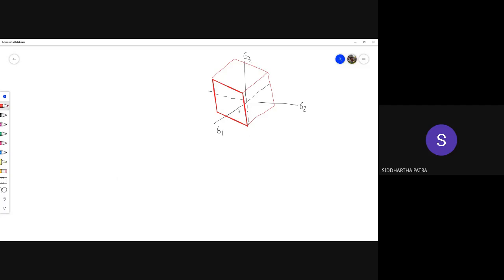The maximum principal stress theory is given by this box, just like it was given by a square in a 2-dimensional plot. The maximum principal stress theory in 3D is a box where each of the planes is either plus sigma y or minus sigma y. So it makes an intercept with one of the principal directions at plus sigma y and minus sigma y, and it's a plane parallel to the plane of the 2 other principal directions. Just like that. It's very simple.